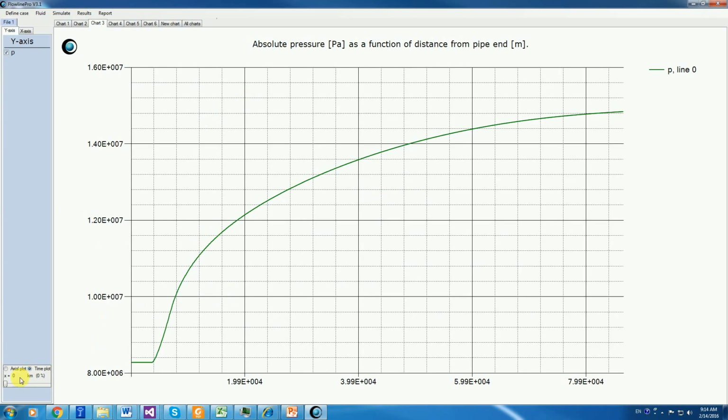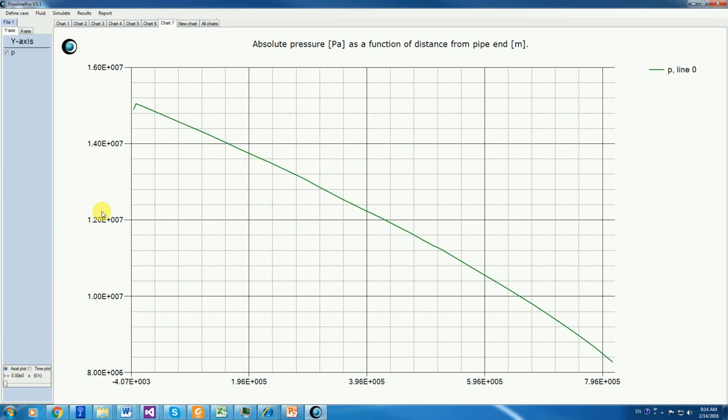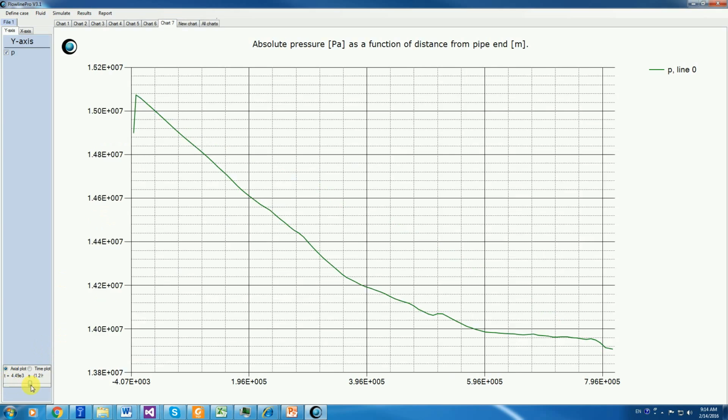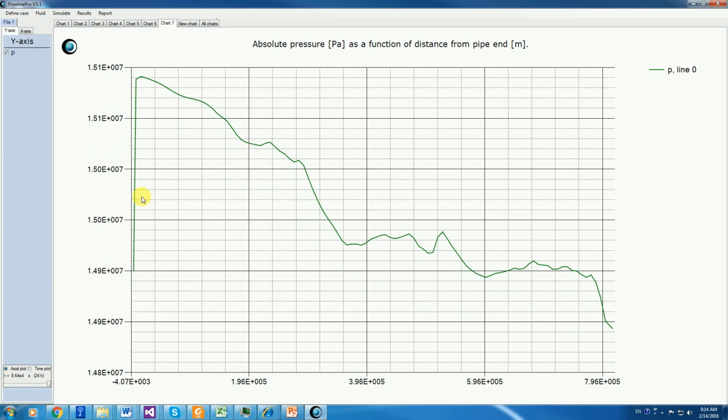Here we have the pressure, and let's look at an axial plot of the pressure. After the full simulation, we see that the pressure is almost the same in the whole pipeline. So that means the reason why it hasn't stabilized cannot be because of the friction, because the friction would mostly make sure there is different pressure along the pipeline due to the frictional loss. But there isn't much of a frictional loss. So the parameter making it so slow to get stable conditions in the pipeline isn't so much the friction as it obviously is the thermodynamic condition, the heat loss from the pipeline.